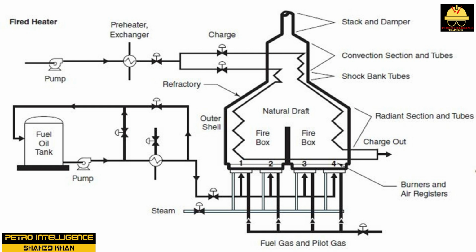A space of 1.5 to 2 feet is considered to be a safe distance between the open flames and the radiant tubes. The burner's flame pattern should be less than 60% the height of the firebox. The radiant section is engineered to distribute the radiant heat evenly. Modern burner design consumes 100% of the fuel with a nominal excess of 10 to 15% oxygen. Excess oxygen in the furnace is carefully controlled as it enters the base of the furnace.